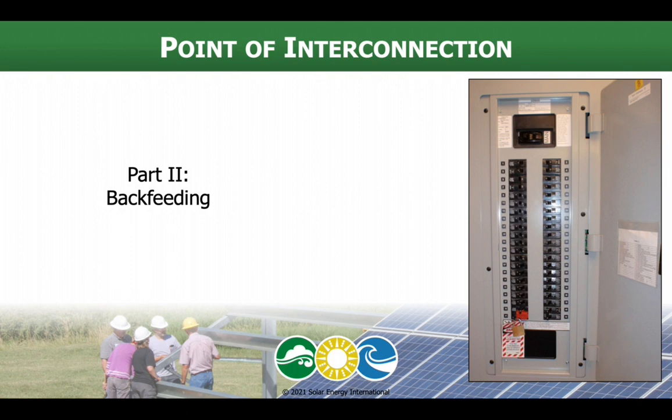Okay, before diving heavily into the rules for different types of interconnections, let's talk about the concept of backfeeding, because it's something we're going to see over and over again, regardless of how we interconnect, because we're not a load. We are a power production source. We're operating in parallel, but we're often going in the opposite direction that primary power sources are used to. They're used to delivering power rather than receiving it, thus backfeeding.